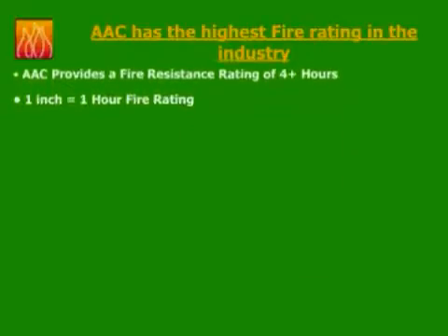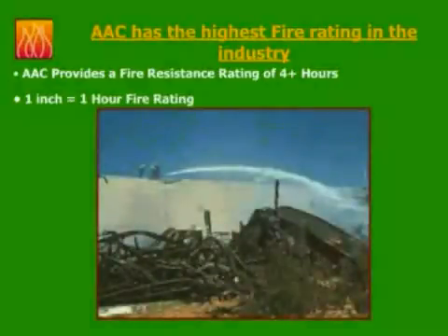What are the advantages of using autoclaved aerated concretes on your projects? AAC has the highest fire rating in the industry for non-load-bearing wall applications. In the United States, Underwriters Laboratories certified AAC for 1 hour per inch, which is outstanding in the construction industry. As seen on this picture, an AAC fire-rated separation wall was used between 2 buildings.